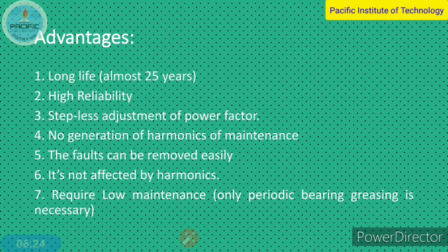So what are the advantages of using a synchronous condenser? It has a long life, almost 25 years. It has high reliability and easy adjustment of power factor, as compared with the static capacitor, in which we have to switch the capacitor on or off based on requirement. In a synchronous condenser, by controlling the excitation, we can easily adjust the power factor of the system. There is no generation of harmonics. The fault can be removed easily. It's not affected by harmonics, and it requires low maintenance. Only periodic bearing greasing is necessary.